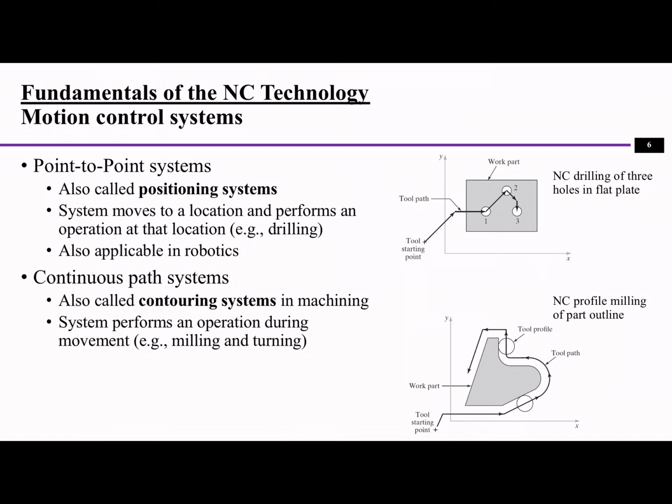Well, the point-to-point system means once you finish the operation at one point, you retract the tool, move to the next point, and do another operation. So this is the difference between the two systems.